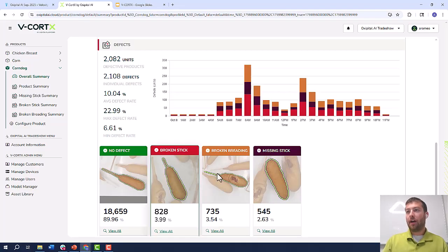We're not showing burned corn dogs here. That is an issue that customers face. In addition to having these metrics on an analytics dashboard, we could in real time send an alert. If we see that there were 7 consecutive burned corn dogs, I can make a pretty good educated guess that the 8th corn dog is also going to be burned. I can also make a pretty good educated guess that someone upstream needs to turn down the oil temperature or increase the conveyor belt to prevent that next one from happening.